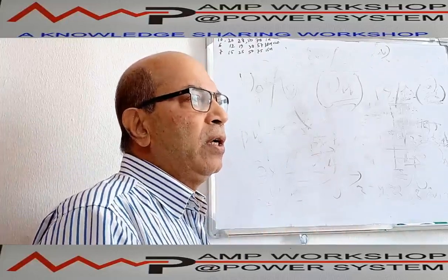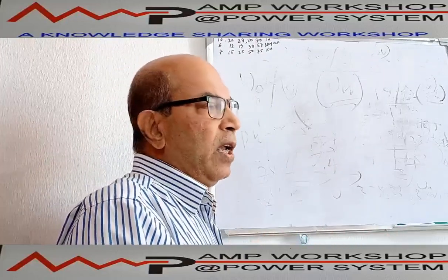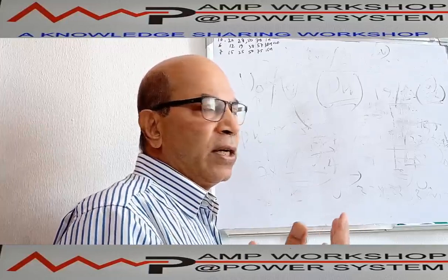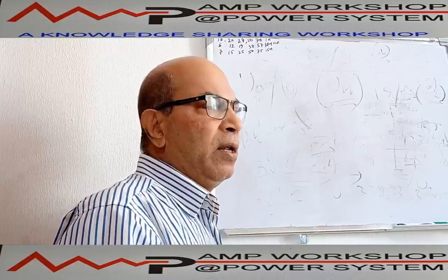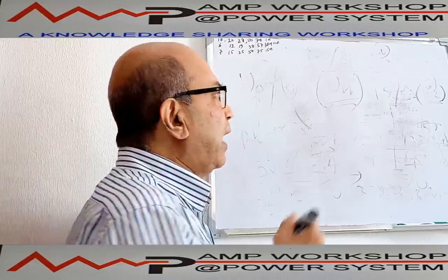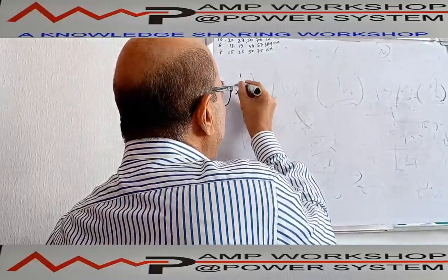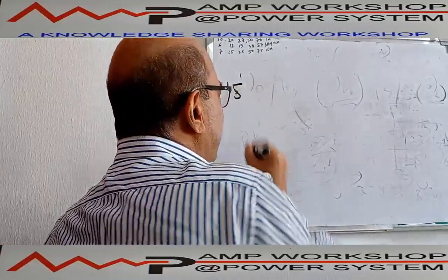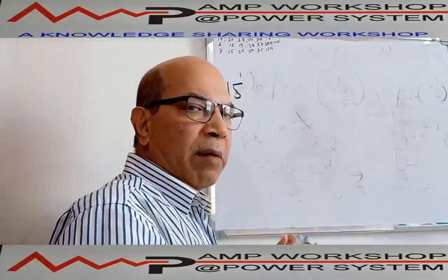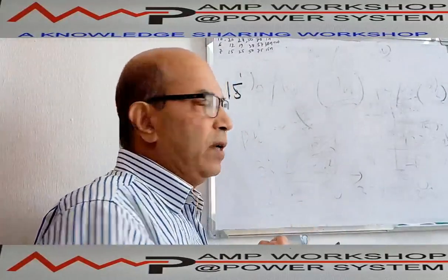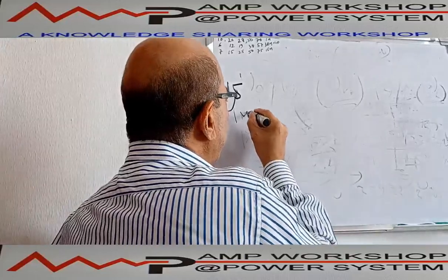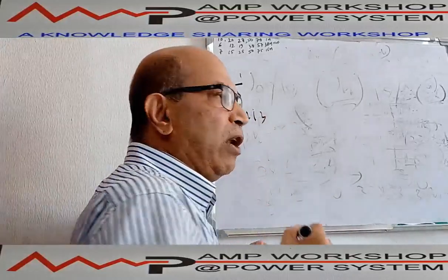And how are you doing the test of the cable? If you check the overvoltage rating of the cable through DC voltage, then that voltage will be applied for 15 minutes. But if the overvoltage capacity of the cable is checked by AC voltage, then it will be for 1 minute. And there is another, very low frequency.